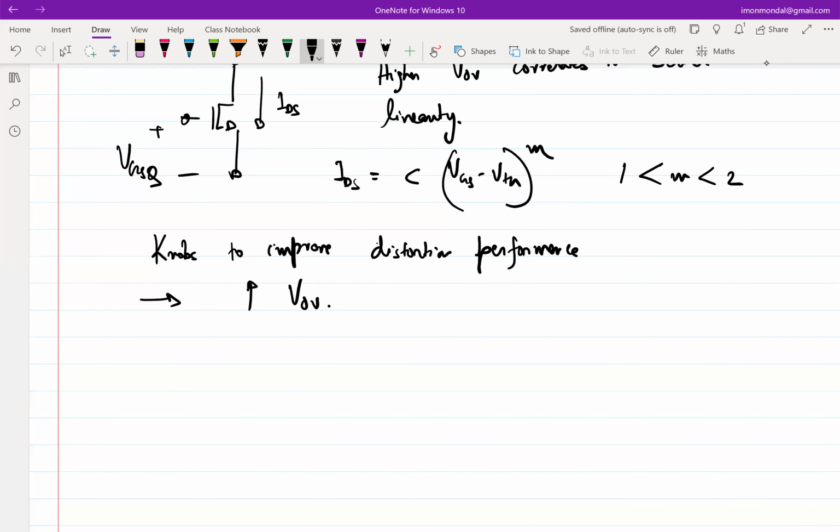That's not very trivial to design, right? Another problem is that you might be able to design something which has decent enough unity gain bandwidth, but you should also appreciate that negative feedback reduces distortion or improves linearity